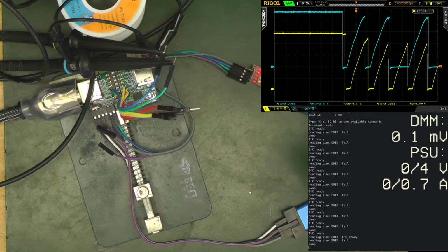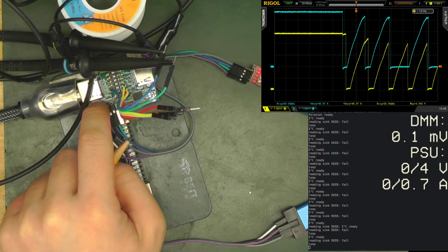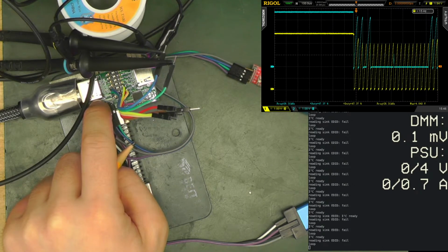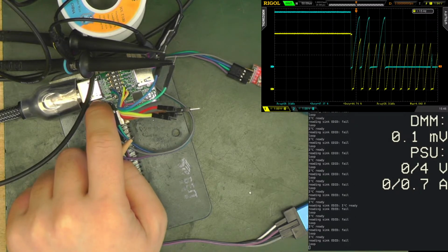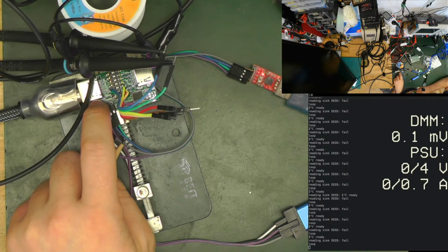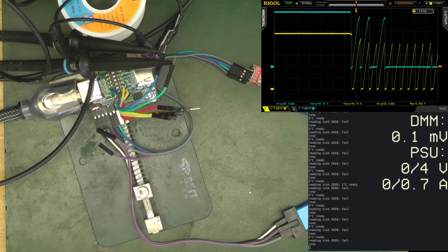Let's try to reset. So the signal is a lot slower. It's not even reading. Why is it not reading? I don't have any pull down signal. Sure, it is slow, but it should do something. Is 2 kilohertz too slow and I actually can't? How did I implement my soft serial? Maybe 2 kilohertz is too slow. I've never tried. Let's try with 10.